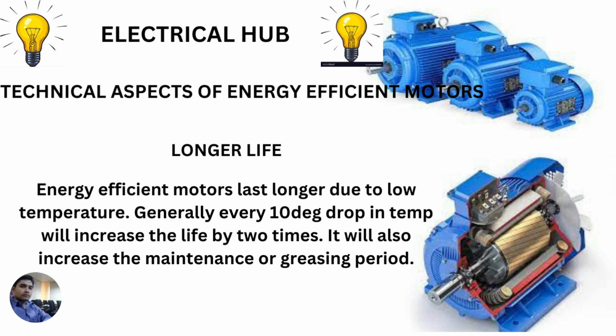In general, every 10 degrees centigrade drop in the operating temperature of the motor will increase the life of the motor by 2 times. It will also increase the maintenance and greasing period. So it will have an economic effect both in the life and in the maintenance.